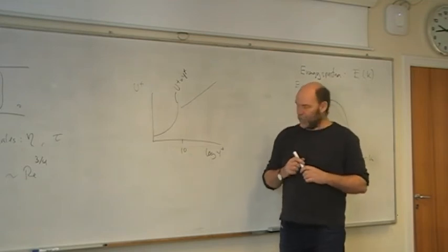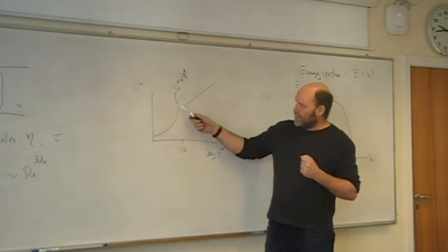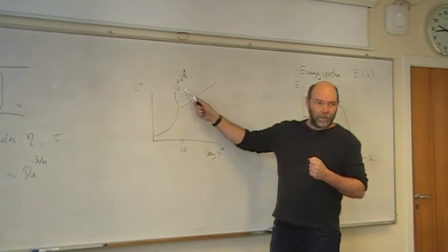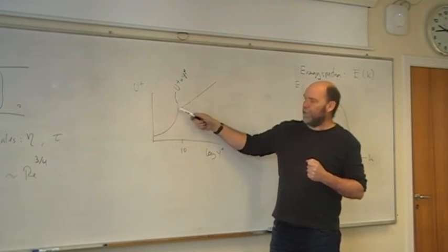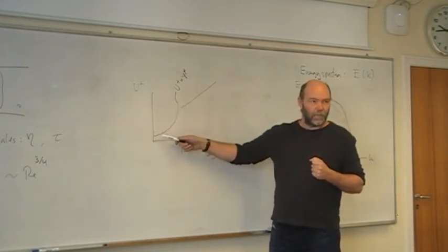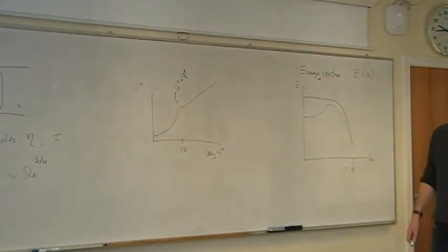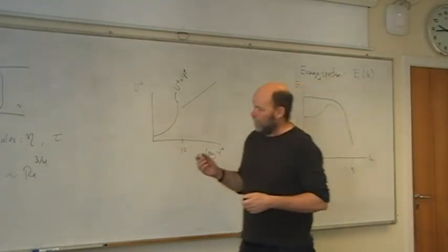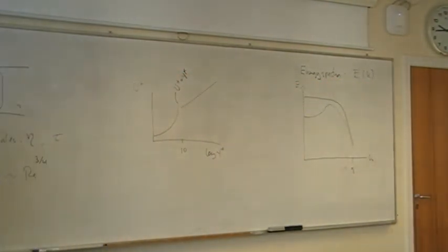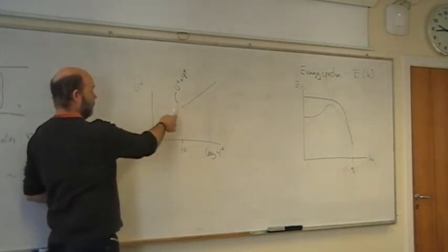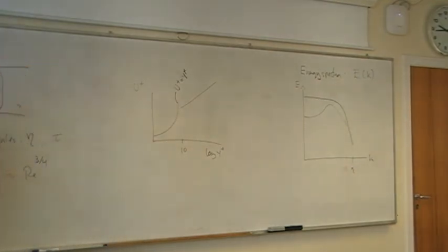So people have sort of the conception that this sublayer here, the viscous sublayer, is a laminar velocity profile. So they sort of assume, okay, then the turbulence is decaying here, tends towards laminar flow. That's a very big lie. Very, very big lie. Because when you look at the activity very close to the wall, within this sublayer in a DNS, the velocity doesn't look like this at all. You will have definitely the most crazy behavior very close to the wall.